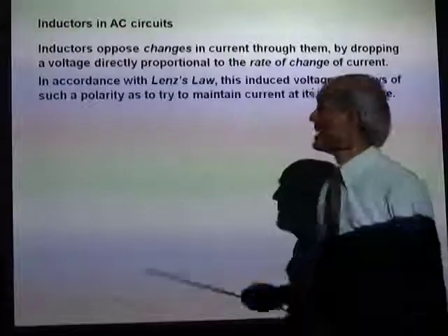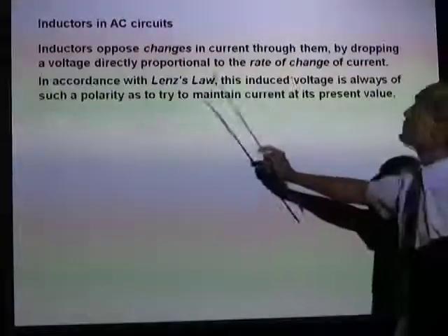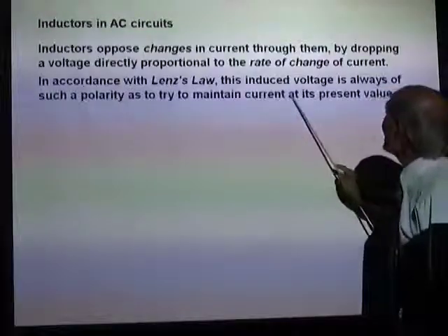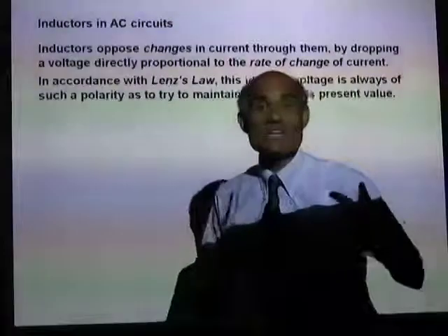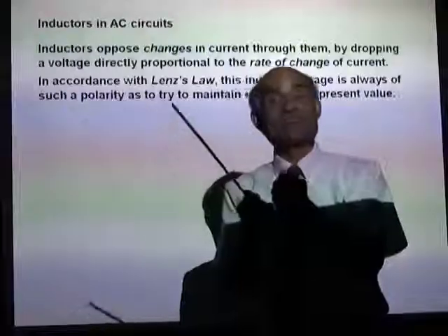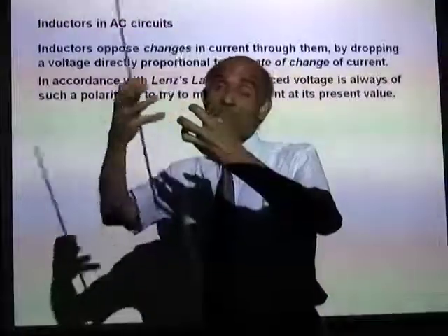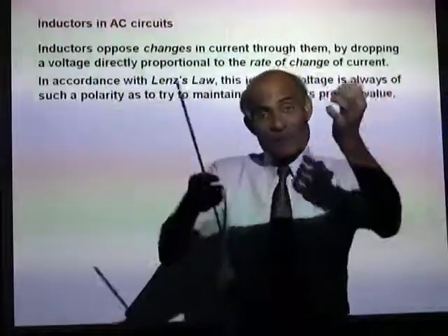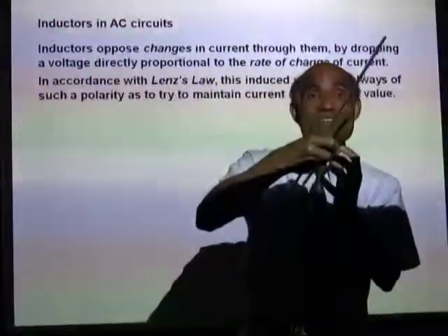Now, in accordance with Lenz's law, this induced voltage is always of such a polarity as to maintain a current at its present value. The tendency of the inductor is to maintain the current at the present value. Why? Because if the current increases, the self-induced EMF will tend to decrease it. If the current decreases, the induced EMF will oppose that decrease.